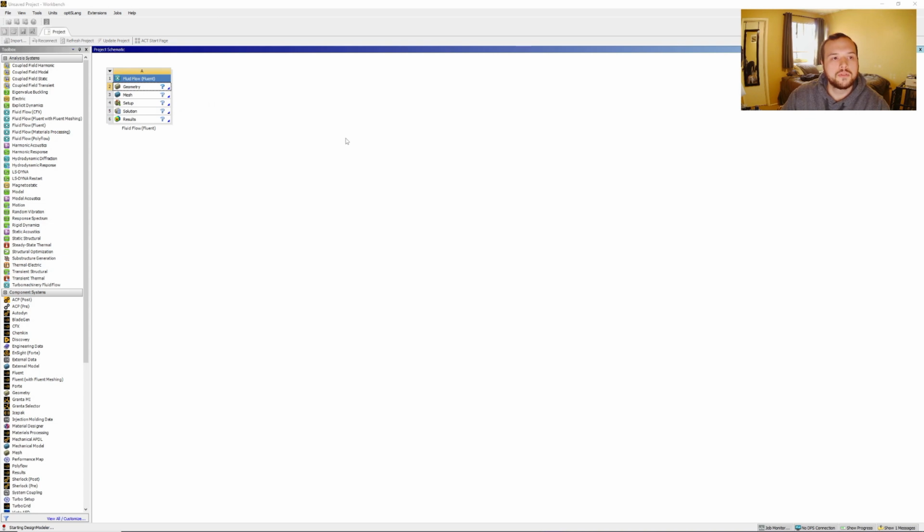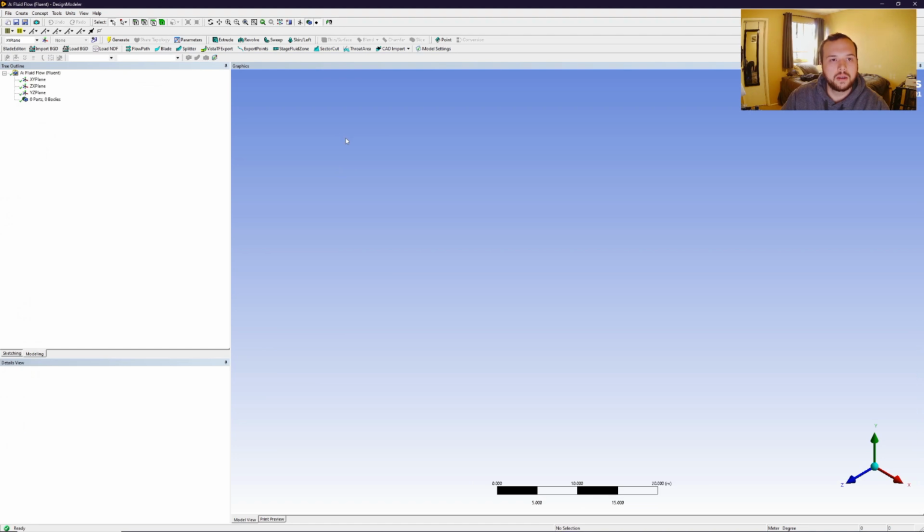So while we had the freedom to choose whatever fluid we wanted, length, height, Reynolds number, as long as it stayed within the uppermost 2500 of the Reynolds number, I chose 2400, and then found my length, height, and my mu value accordingly. I chose to do a smaller height for my pipe, and we'll see that it is going to be 0.01 meters or 1 centimeter.